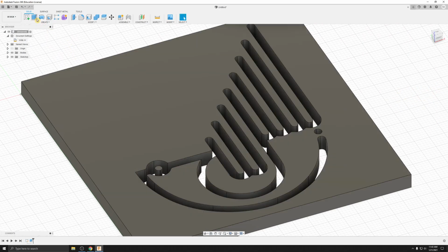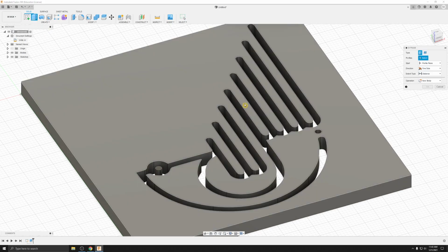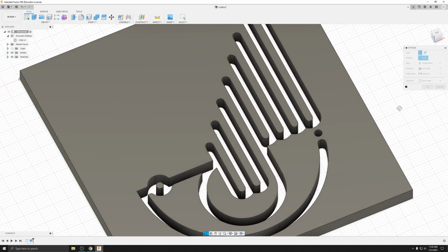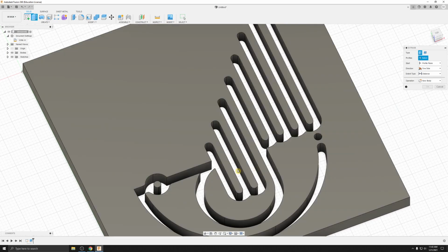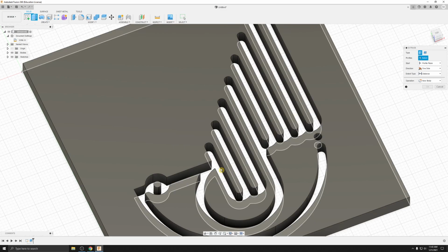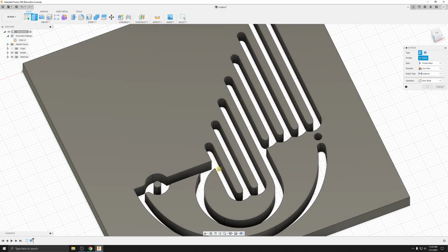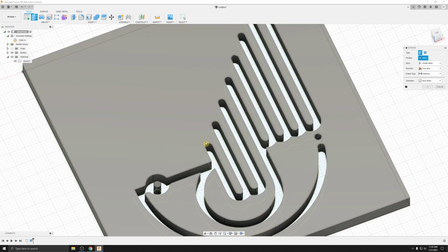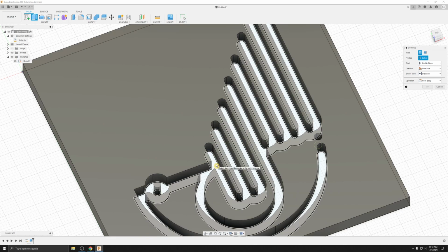Okay, I'm going to just press this just for your thing. Okay, so I'm shift, middle mouse clicking, and remember when you do your first extrude, see my sketch is in there, so I can't select any face or anything here. So I need to go over here, select the arrow down, and enable it so I can see my sketch. So now I can select this plane over here.